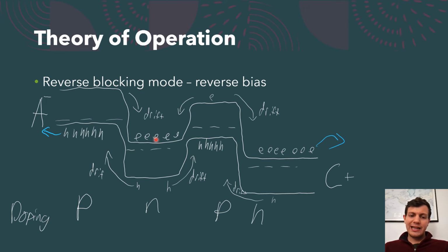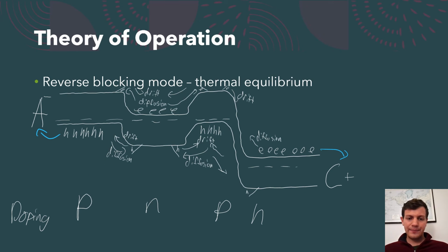And any currents that happen to flow in here will quickly get annihilated with the electrons, which in turn will further increase or decrease the potential, which raises the Fermi level up to meet the level of the anode terminal over here. So as you can see, once this drift current happens, moving charges from minority charges, and once all the minority charges are either eliminated or have drifted back into where they become majority charges, the potentials are going to be restored, as we see in this next diagram.